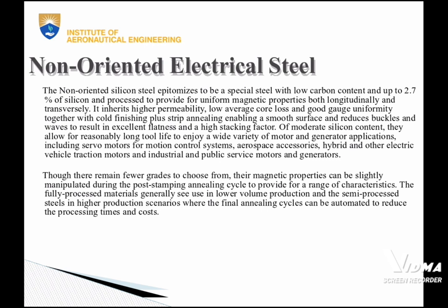Non-oriented electrical steel. The non-oriented electrical steel is a special steel with low carbon content and up to 3.5 percent of silicon, and is processed to provide uniform magnetic properties both longitudinally and transversely.